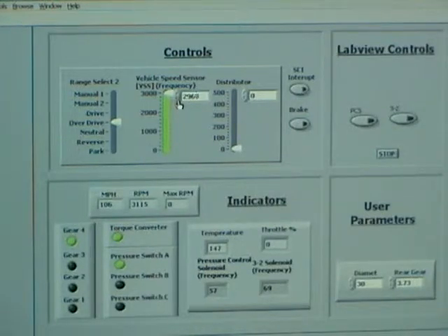We're actually able to change the speed slowly, so not a lot of deceleration, but we are able to change it, and the torque converter never unlocks. But if we do a large change, you'll see that the torque converter does analyze that there was too much change that would cause damage to the engine, and it unapplies itself. And we never left fourth gear, so it's not because of that, but it was actually because of the large changes that you see in the speed.